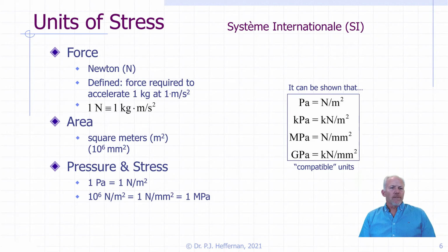So, in our review of statics, we talked about units. We will be using SI units, and thus the load will be measured in newtons or kilonewtons, and stress will be measured in pascals or megapascals. We will, of course, insist on equations being completed in compatible units. Because civil engineering materials are typically strong, their material strengths are usually referred to in megapascals, which makes newtons and millimeters desirable because they go together to make a megapascal. That said, we often have larger loads and longer span lengths, so we often will start off in kilonewtons and meters, but need to convert to newtons and millimeters once we are looking at the cross-section and the stress.